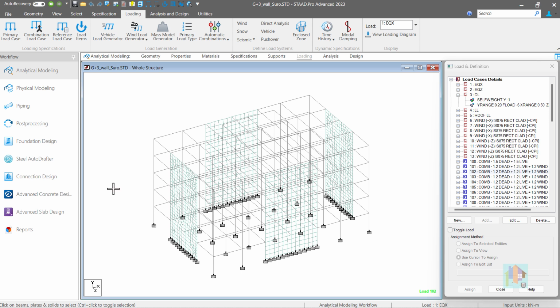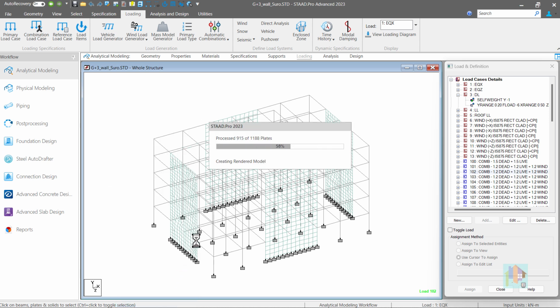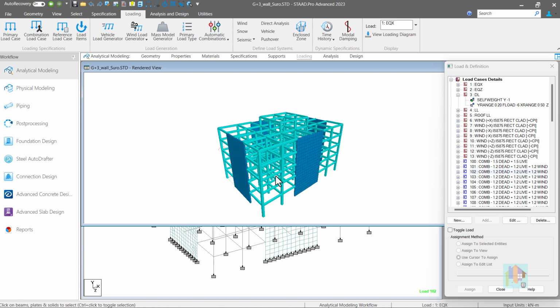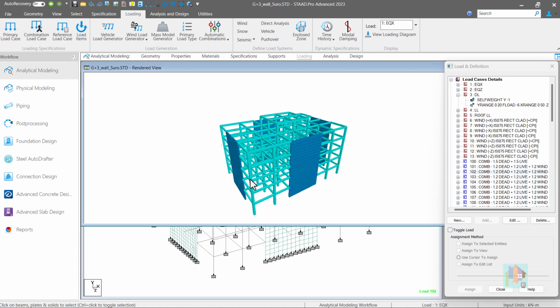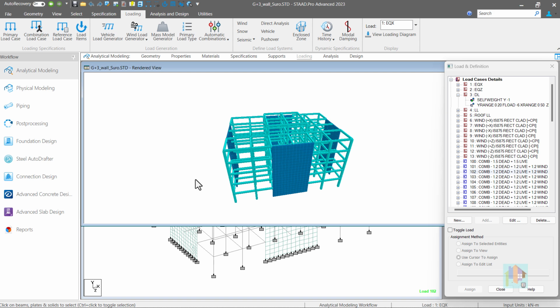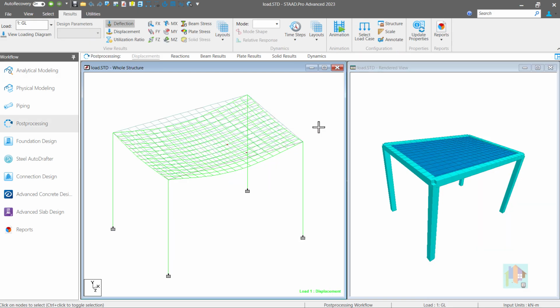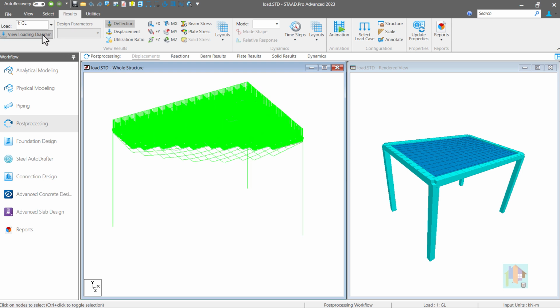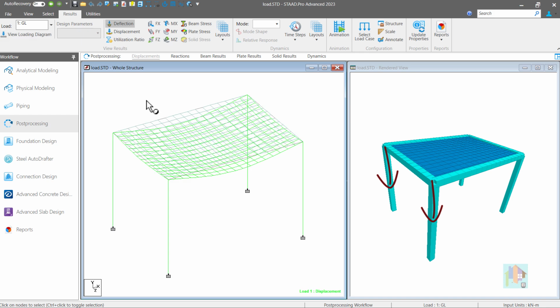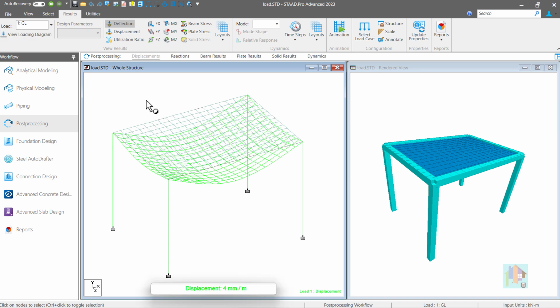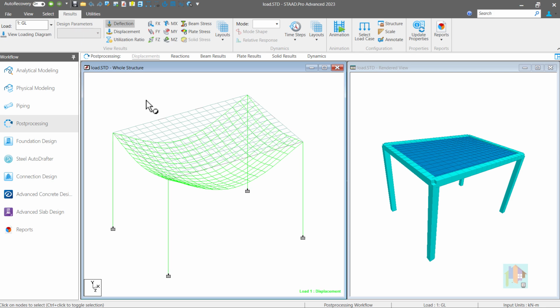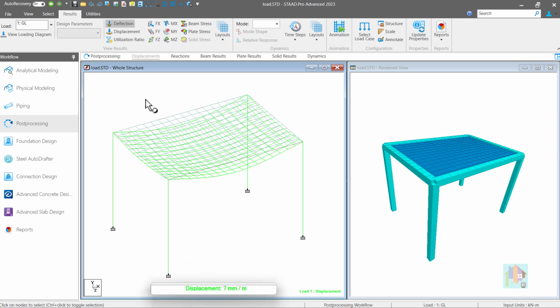This structural model is incomplete, as we have ignored a very important element during analysis which can change the overall design result: the concrete slab present at each floor level. When a gravity load is applied on the floor, concrete slab transfers this load to the supporting beam and column. Stiffness of the slab doesn't contribute much except reducing the out-of-plane deformation. Deflection value must be within a limit.